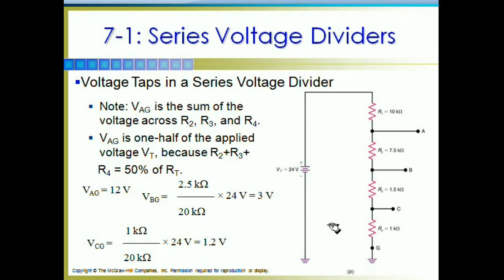All right, and here we're going through each resistance. All right, they're starting down here and performing the same calculations I just did. Oh, the thing I forgot. Okay. It was easy to calculate just the voltage drop at point A because I was going across R1. At point C, I just went across R4.